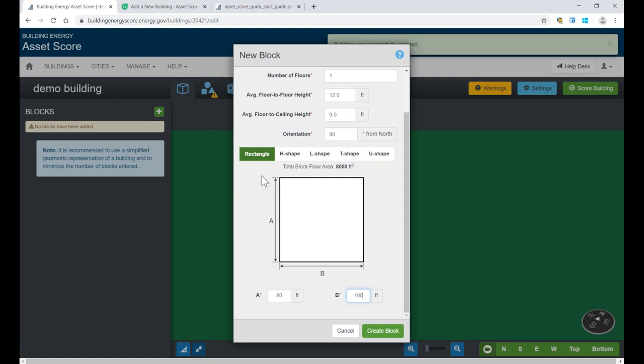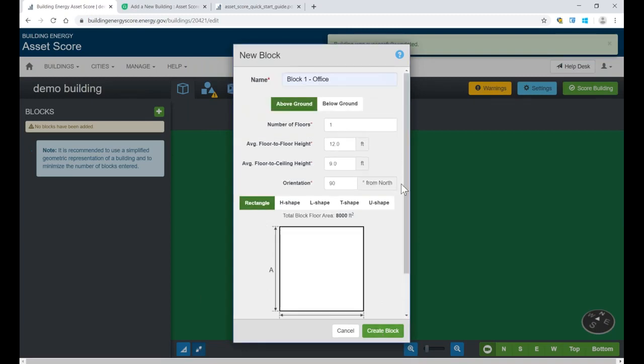For example, for a courtyard, you can use 2 U shapes or 2 L shapes, and I'll show you how to move those around in just a moment to get an approximation. And once again, I'm emphasizing approximation; your building does not have to exactly match the footprint, just as close as you can.